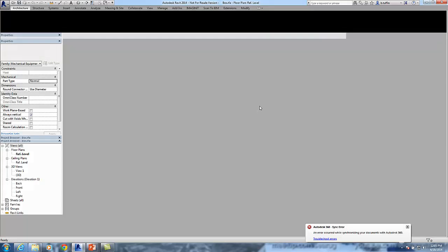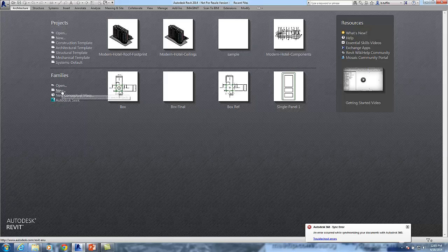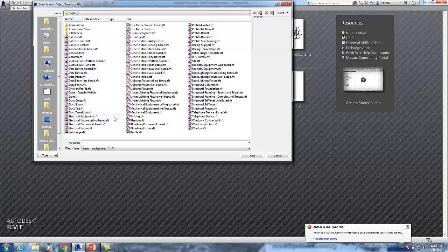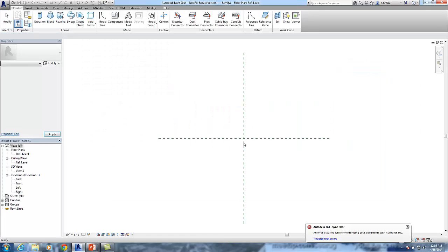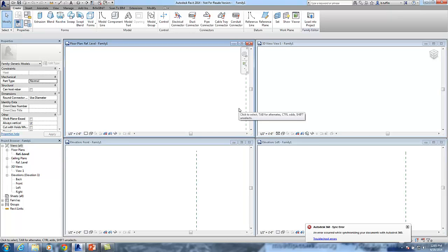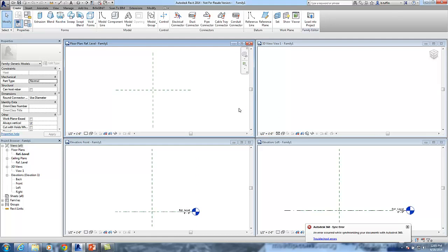Okay, so in Revit here, I'm going to go ahead and close out of that file. We'll take a look at it here in a minute, but I'm going to start a new family. And in this case, I'm going to do just a generic model. Now, as soon as I start this family, I want to work in a window tile mode. A lot of the times I recommend staying in at least a front right plan isometric, having at least those views open, because we're going to want to be able to access and manipulate it and get to information as much as possible.